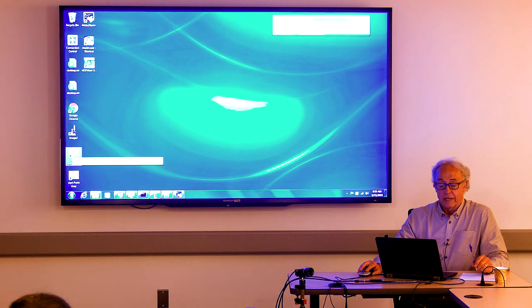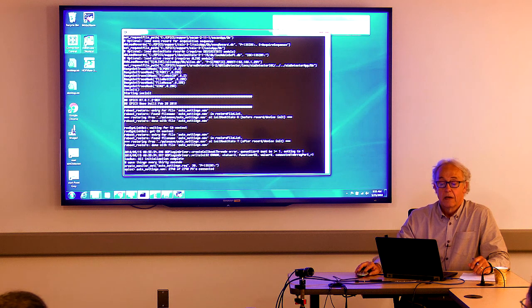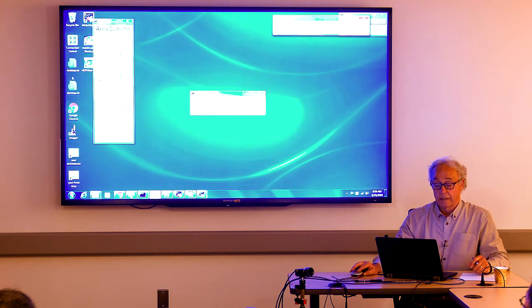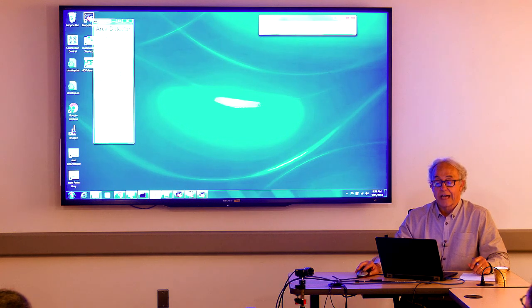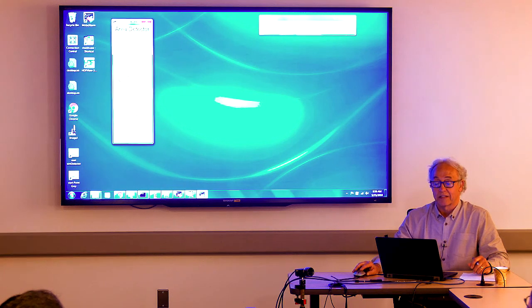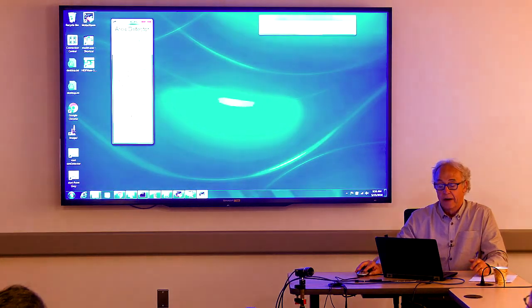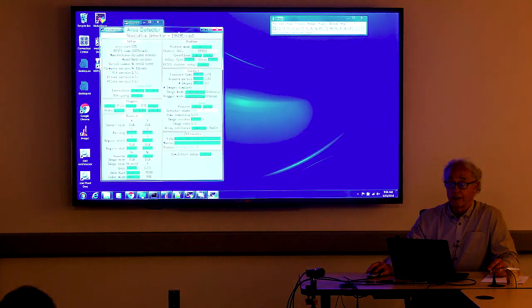So I've got a shortcut here that basically just CDs to the IOC boot directory for this SIM detector and then starts the SIM detector application. And then up here is going to launch MEDM. I'm going to kill that window. For now, we don't need the IOC window, don't need this main MEDM window. So now, this is a top-level screen for area detector, which basically has the ability to launch any of the detectors that are in the package. You guys probably wouldn't use it, but I do. So I'm going to launch here the simulation detector.